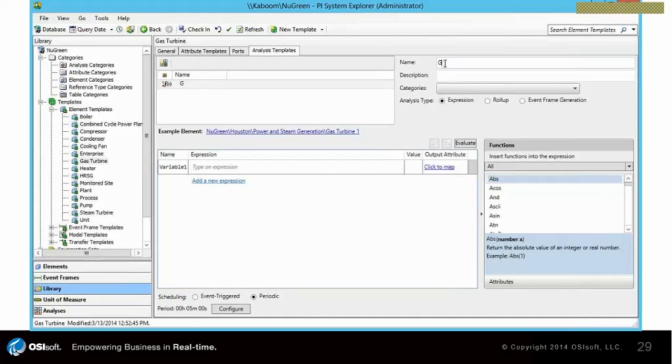One of the things that you want to do is make sure that temperature measurements out of the back end of the gas turbine are all within a reasonable deviation from each other, because otherwise you probably have a hot spot in the output stages of your gas turbine, and that's a bad thing. So let's start this video quickly.